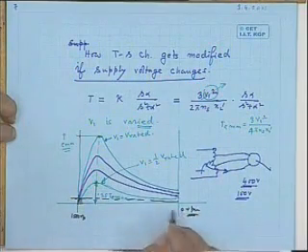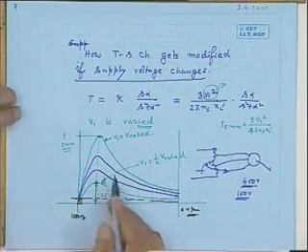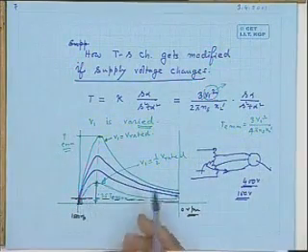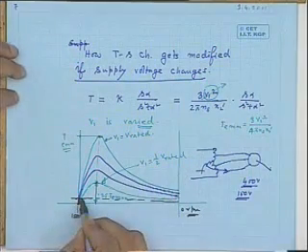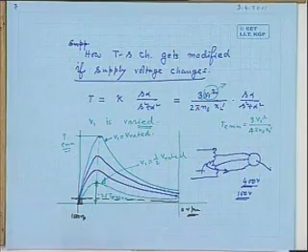What is this level? 1500 RPM. What is this one? 0 RPM. So what is the variation of speed here? Suppose full voltage is applied, the machine is running, what will be the no load speed? This one. Suppose half voltage is applied, the no load speed will be this much. Only little variation. It is difficult to distinguish between these two.